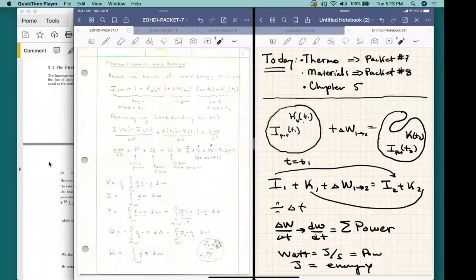So for example, kinetic energy, if this had been an entire rigid body, would have been a pretty easy affair as undergraduates, because we know that's just going to be 1/2 m v dot v, where there's a single velocity for the entire object, and it basically moved as a rigid body. That's obviously not going to be the case now for a continuum, because each little piece of material is moving with a different velocity, and therefore we have to integrate over all of these little pieces to compute the total kinetic energy. That's just one example.